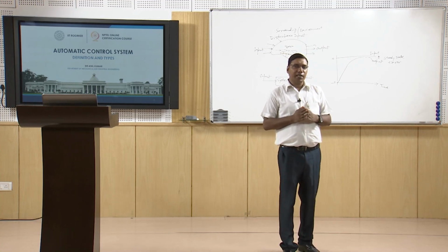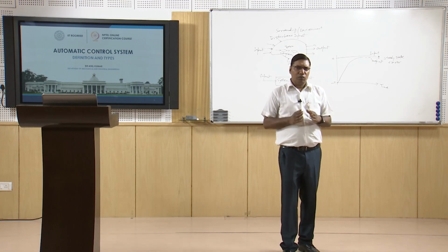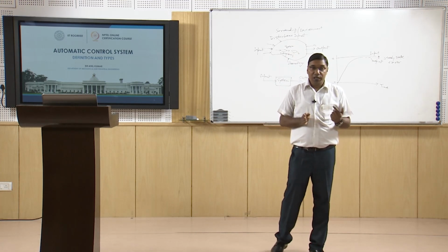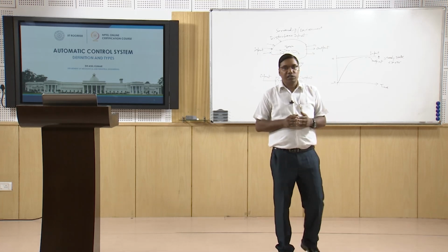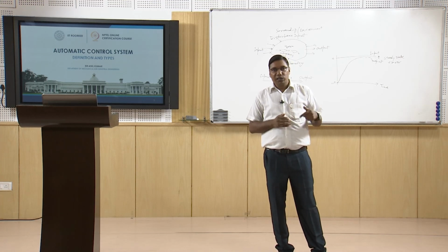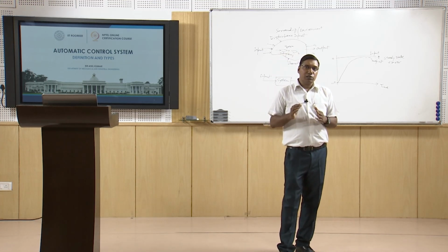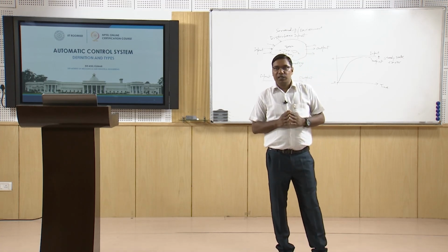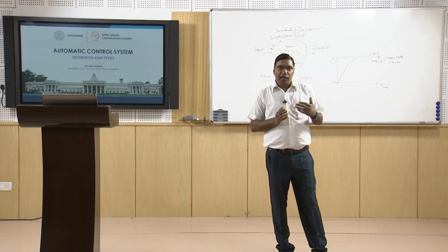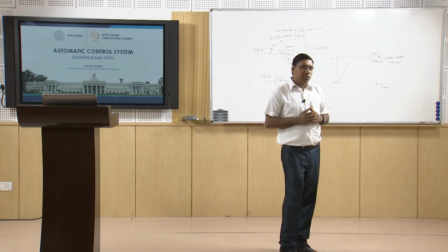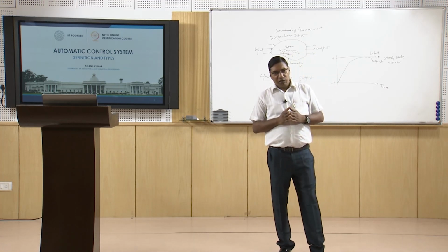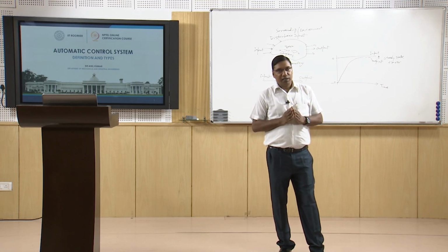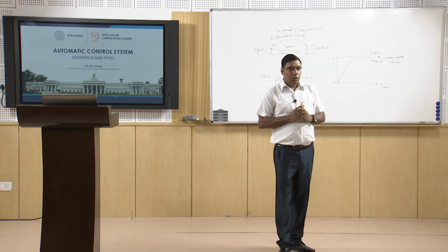So we can say that they are less sensitive to these disturbances. While in contrast, the open loop systems are very much sensitive to the disturbances. If the disturbances are more, the open loop system's performance will be affected very much, and they will lose the actual desired output, and the steady state error might increase. So therefore open loop systems can be said to be very sensitive to the disturbances.